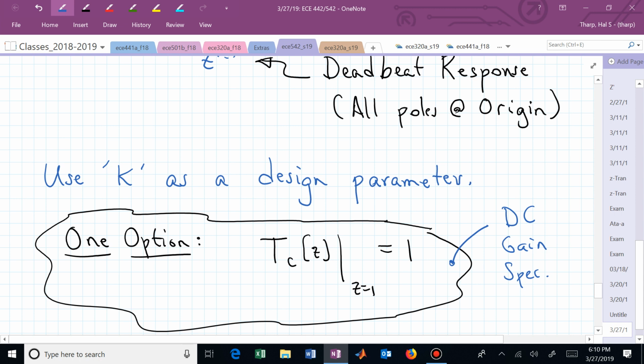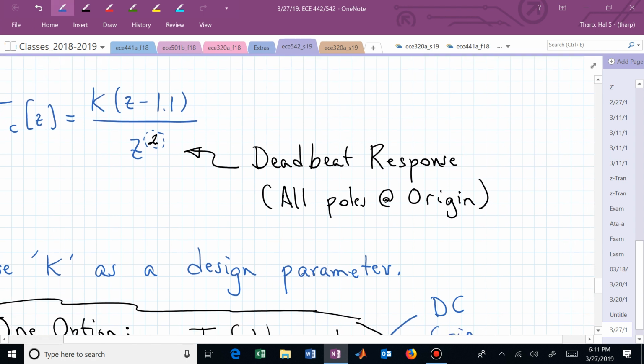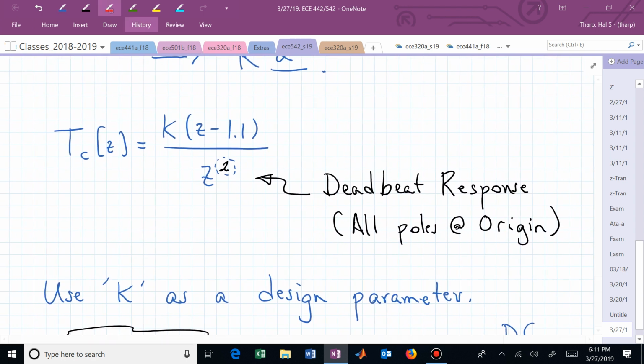And there may be other reasons for picking k. You might want to put in another zero factor, suppose I now put in a factor that was like this. Now I have an alpha and a k to play with, but what do I need to adjust anything else before I move on to try to find my c?